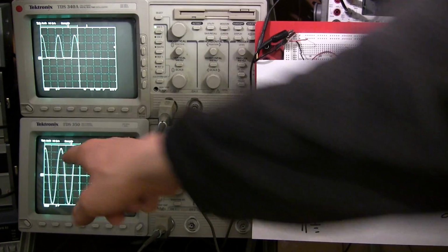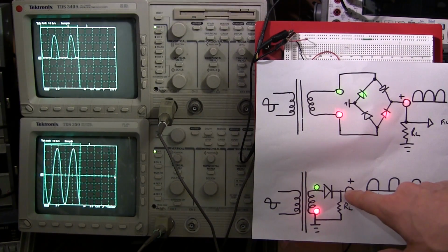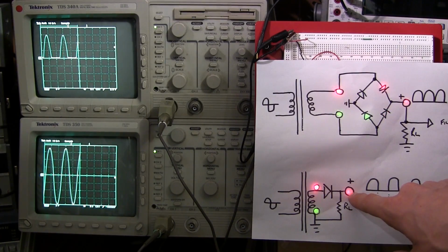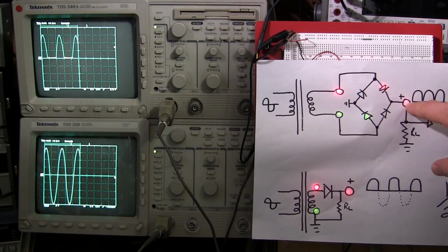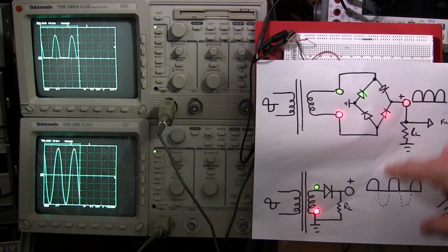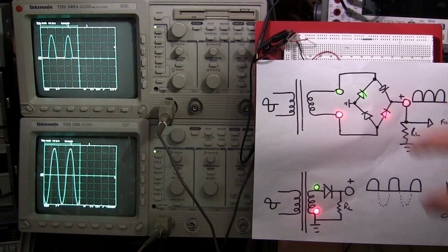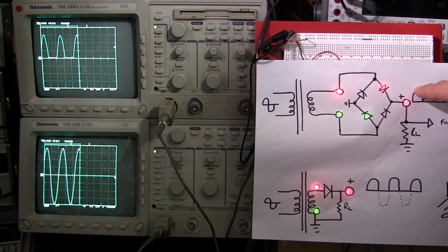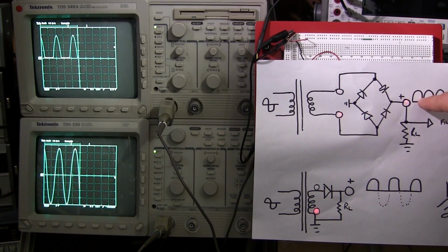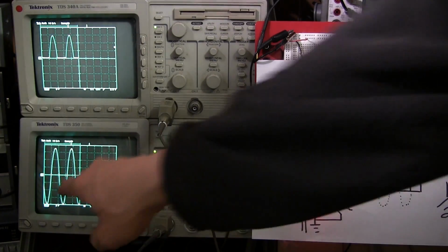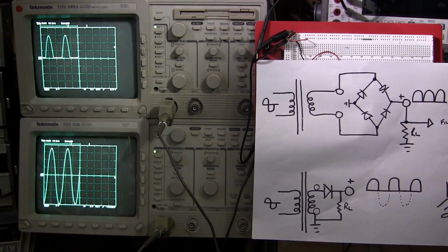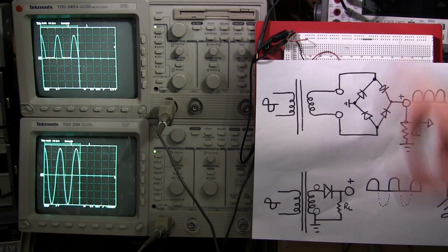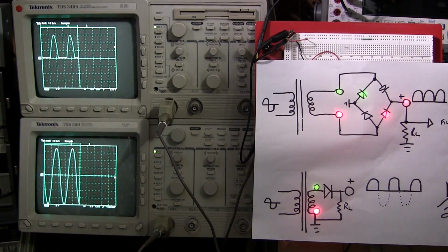So you can see on the positive half of the cycle, this LED is on, whereas on the negative half of the cycle, it's off. You'll see this one come on again quite shortly. Now you'll notice that this one here is turning on even on the negative half of the cycle, and that's because this is a bridge rectifier, whereas this is only half wave. So as this one is on the positive half of the cycle, it turns on, and now that it's on the negative half of the cycle, it's also turning on again. You can see the negative half of the cycle here. And that's just because this is switching this around. It's continually switching that around so that we continually get positive pulses.